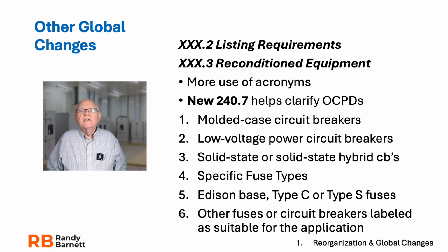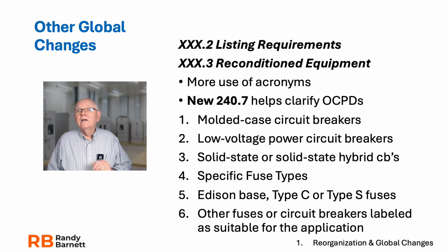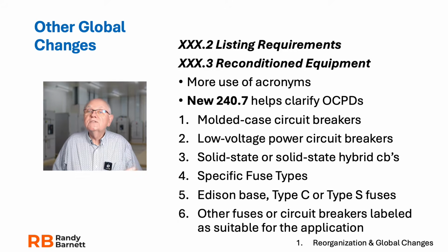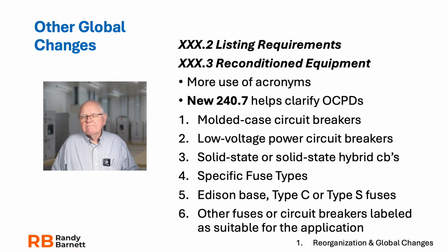We all know molded case circuit breakers, low voltage power circuit breakers, solid state, and what does it say? Solid state hybrid circuit breakers. Wow. Specific fuse types, plenty of those. The old Edison-based fuse, type C or type S fuses. And then, that term that we often see, other fuses or circuit breakers labeled as suitable for the application. So anyway, that list, take a look at that in 240.7.